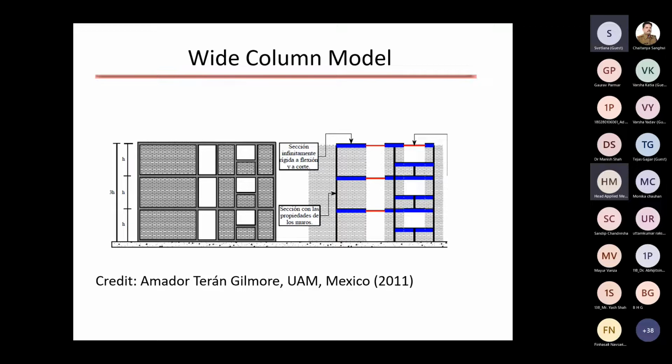I will talk separately, in more detail, about modeling of these parapet portions of the wall. You can see here, for example, that there is another black element in the middle, below the window opening, which models the parapet, and then another rigid element which models this parapet portion.